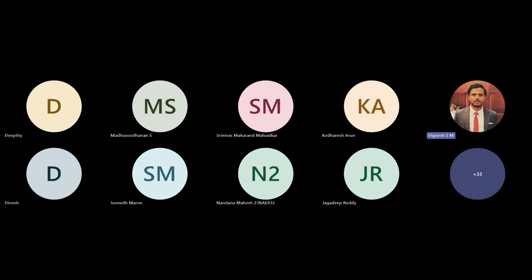And yes, as you mentioned, ma'am, the turbulence model also makes a difference. But I can say SST k-omega is somewhat best for external aerodynamics. Yes, you can rely much on that. Other than that, if you go for some other turbulence model, it will definitely have an effect on the computational time also.